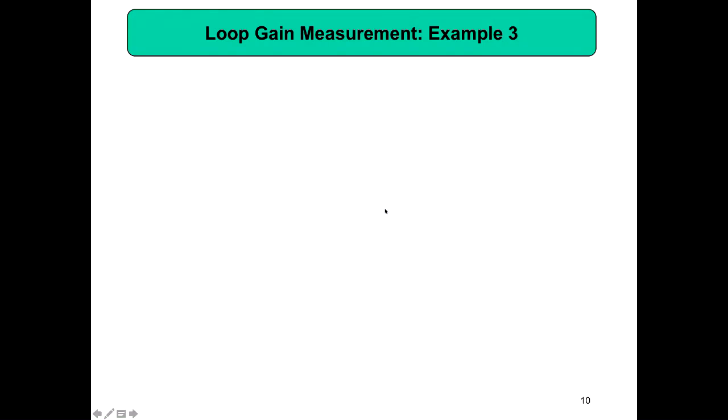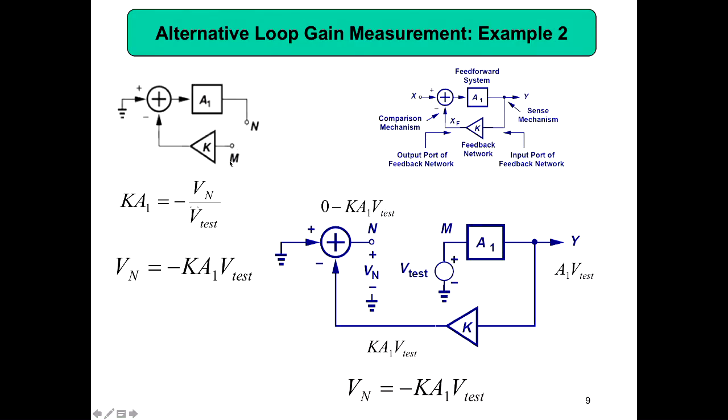So that is the reason when you break it, you have to connect your signal here, because then signal will be going to the input of the amplifier and then coming out. Even when you break it here, we are connecting signal here, because signal is going to the input, not here. Signal is going into the input of the amplifier and then coming here and then like this.